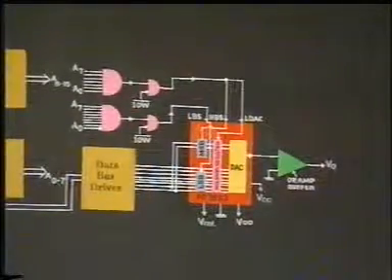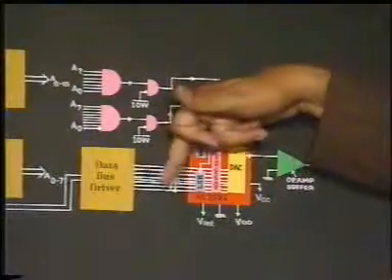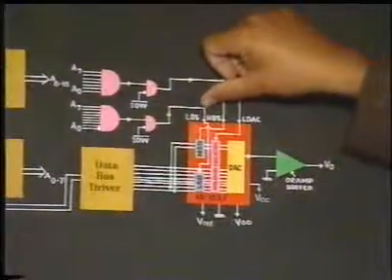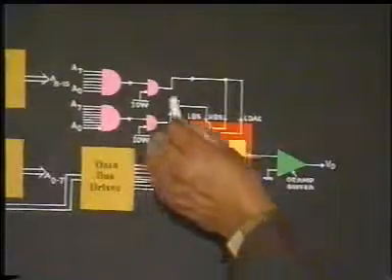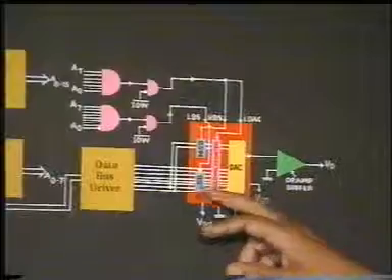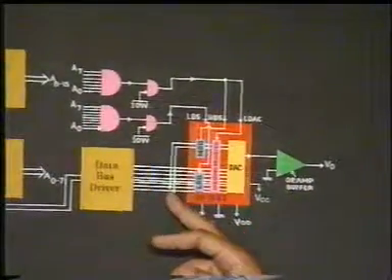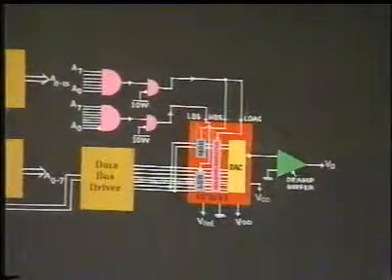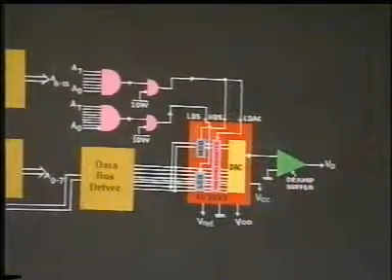Whenever a conversion is to be carried out, the microprocessor sends the lower 8 bits first and enables this port by sending the enable signal on the LBS line through some port decoding. So the first 8 bits have been latched into this LSB port. Then it sends the second sample, which contains only 2 bits, to be latched into the MSB, the second port, which is enabled by the HBS control signal.